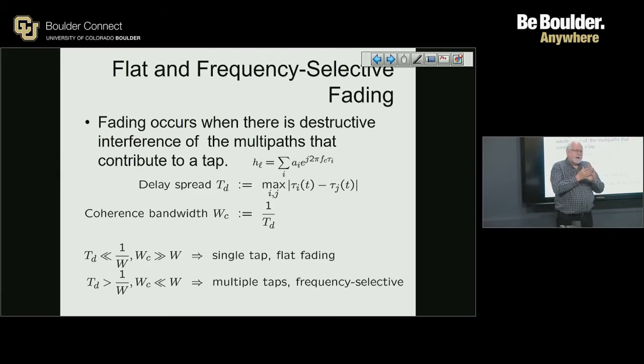If you measure the reflections, let's say you send an impulse out, just like in a tank of water. If you dropped a rock, you would see the wave go out, and there would be the wave that reaches the receiver first, and then there would start to be all these reflections. So we need a way to quantify how many reflections there are and how strong they are in an environment. And delay spread is that. Delay spread is a measure of how strong the reflections are and when they occur. More formally, mathematically, it's the centroid of the observed reflections after the main path.